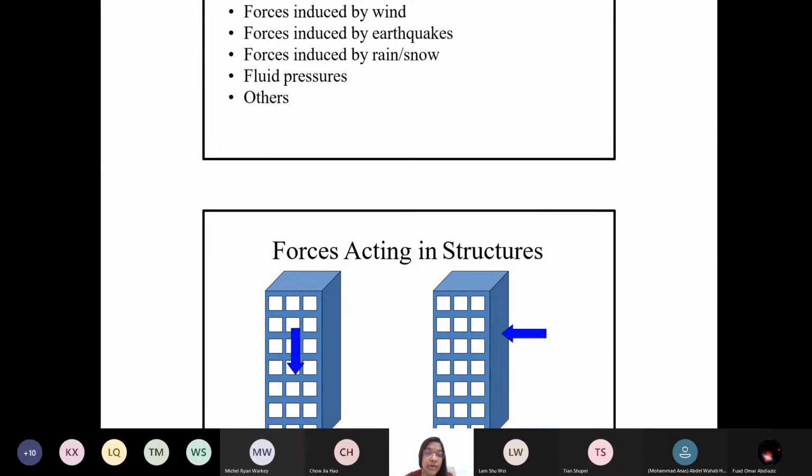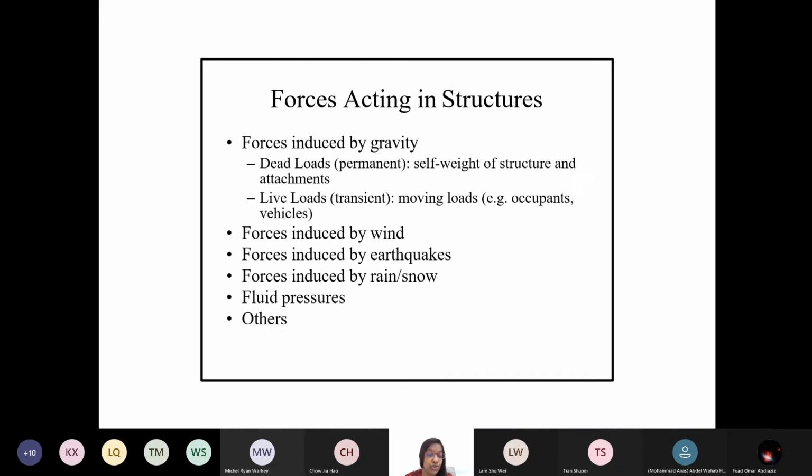Okay. But this list is not stopped. It is not just 1, 2, 3, 4, 5, 6. The sixth is here due to electric shock, electronic signals. We do not know which one it is, so these types are also coming up. About six types of loading are there. And the gravity load is of two types: dead loads, which are the self weight of the building itself, and live loads due to other objects, right? Moving objects, stored objects, running objects in the building, or by all occupants.